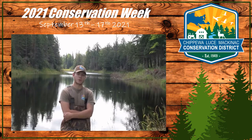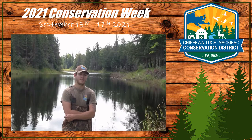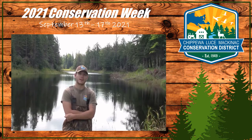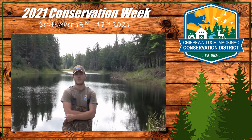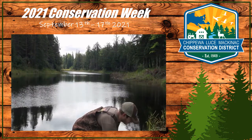And then the fourth parameter we're going to look at is temperature. Temperature we're going to take in degrees Celsius, and it's just the temperature of the water. The temperature affects growth rate of organisms, and also can affect conductivity, dissolved oxygen levels, and all other parameters. So with that being said, the equipment we're going to use today is Vernier equipment.